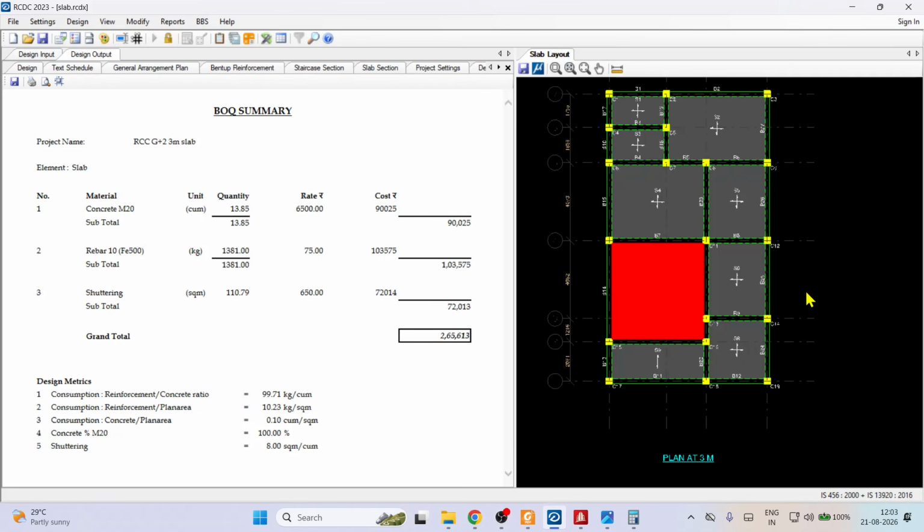Labor cost varies from place to place. It varies from 25 or 35% of the total material cost, and sometimes it reaches up to 50%. Also include 10% wastage. So 11 lakh, then after a 50% increase it's approximately 16.5 lakh, and 10% wastage, 2 lakh more. Approximately 20 lakh for 4 floors. So one floor is approximately 4 to 5 lakh.